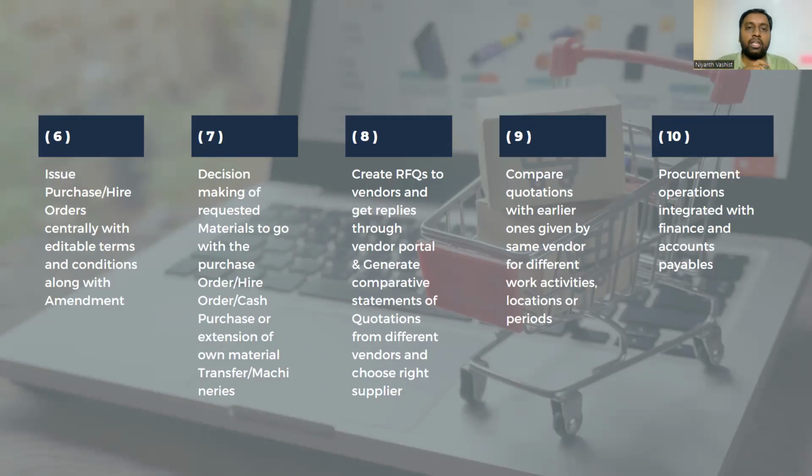So if there are some materials, I'll give an example. We have something called an adhesive. Adhesive is basically used with lightweight blocks. Instead of mortar, we use chemical adhesives. These adhesives also come in powder state, similar to mortar. You just mix it with water and put it on the masonry of lightweight blocks. The thickness is around 3 mm to 4 mm, which is very less compared to the mortar. Hence, for lightweight blocks, adhesive is chosen.